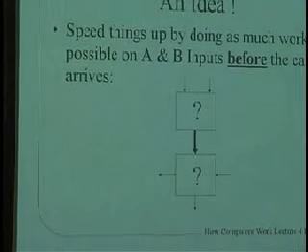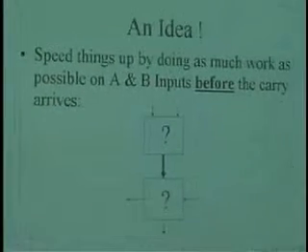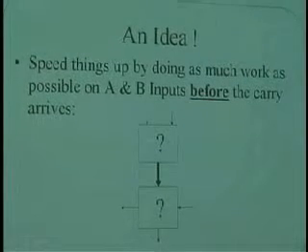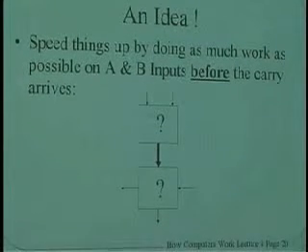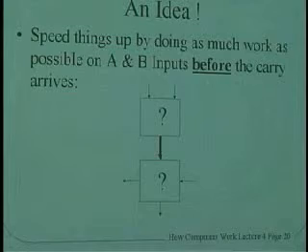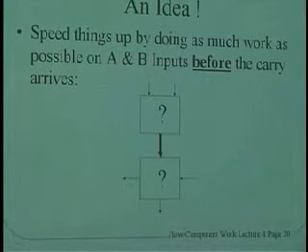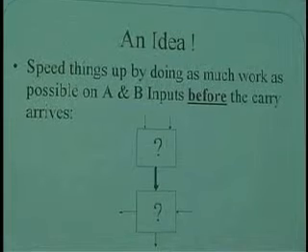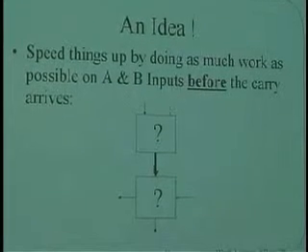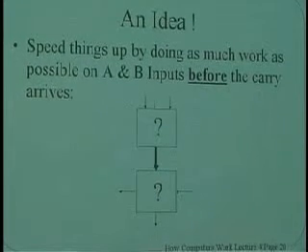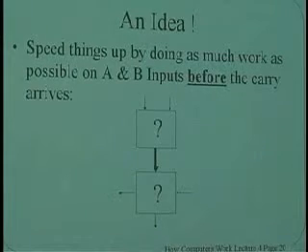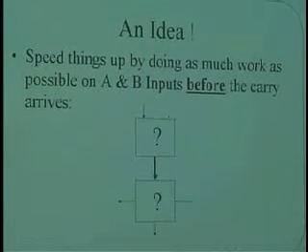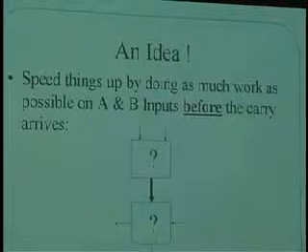So we see how we can implement the sum using a parity tree like this, and we see how we can implement the carry out using a sum of products form that we can simplify by using a K-map. But still we're left with an adder structure that's a series chain of these things and kind of slow. So let's talk about exactly what's going on inside of this adder and see if maybe we could speed things up a little bit.